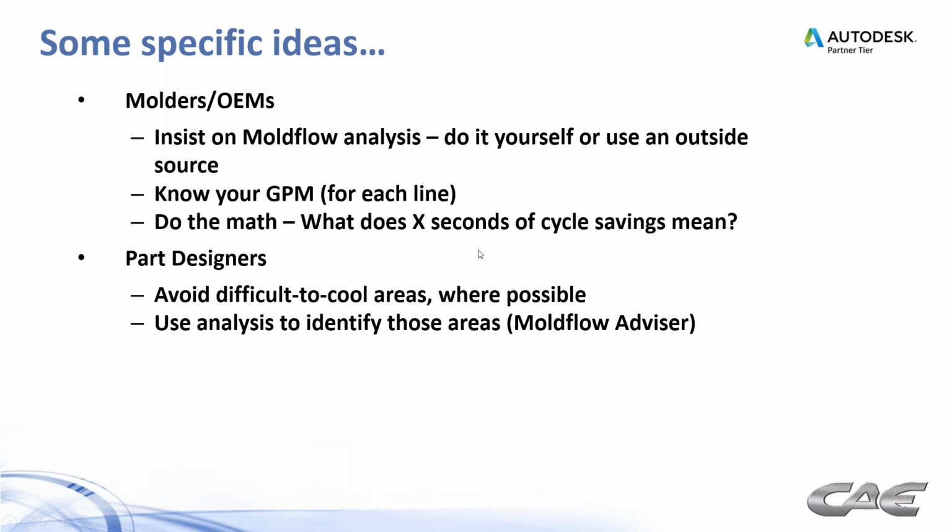Everybody, in my opinion, should have some level of Moldflow on their desktop, even if it's just the Moldflow Advisor. Put that on your desktop. If you're a part designer, you can put your part design in there, and very quickly identify what would be a red flag in terms of cooling.